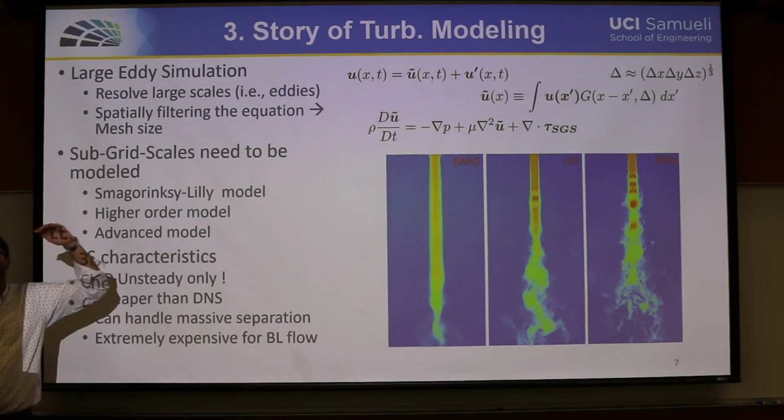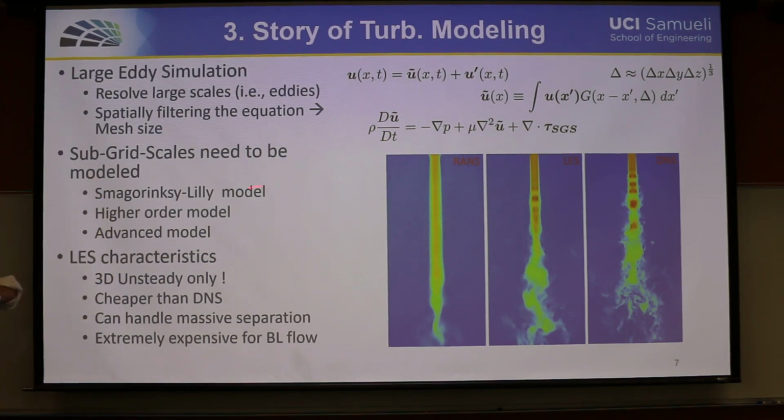They do not take the LES solver as it is until you reach the no-slip boundary condition. They actually model the wall behavior inside the LES solver to relax the very expensive requirement for computational hardware. Because otherwise, you could go and solve DNS. It's not going to be the same cost, but it's very costly.